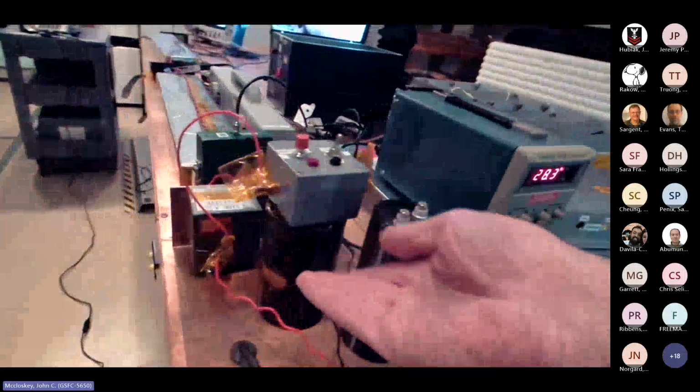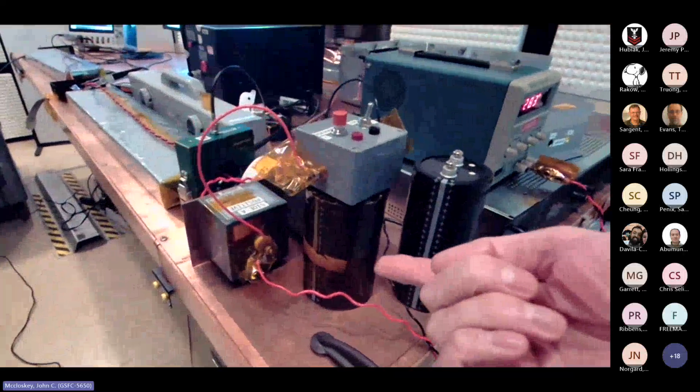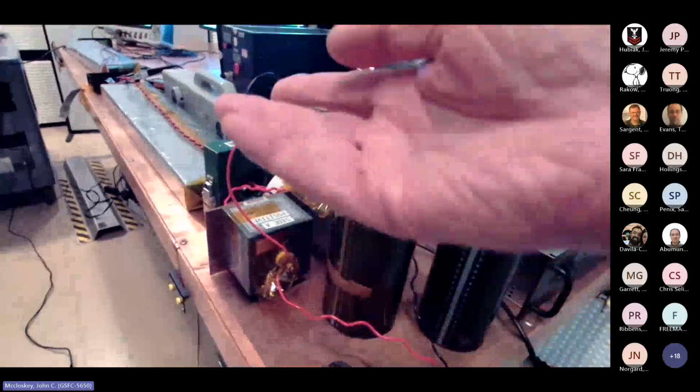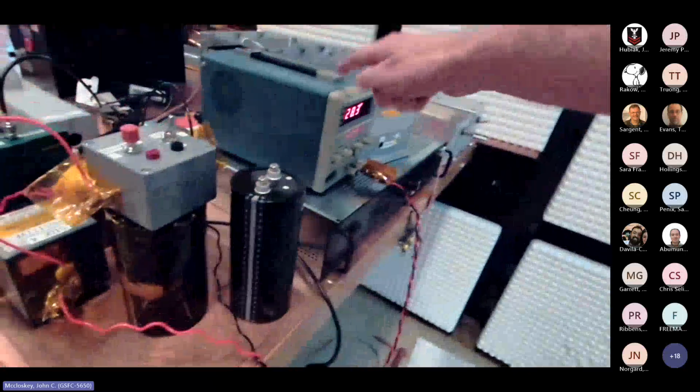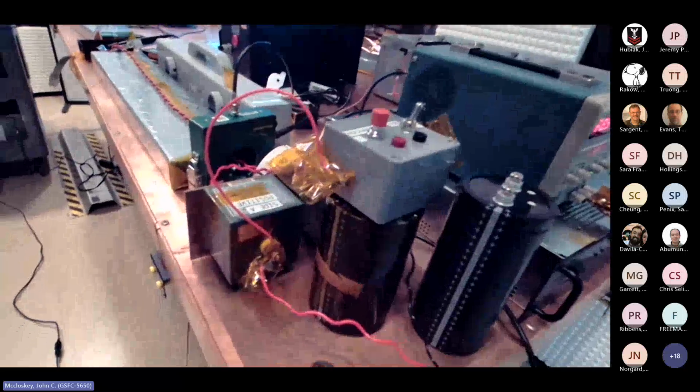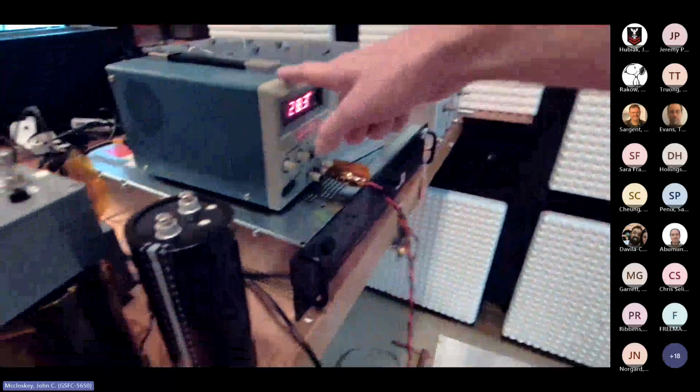It's essentially the same as putting decoupling capacitors next to your ICs on a PC board, so that the high frequency currents are drawn from these capacitors and not from the supply. So the source impedance that your EUT sees is this, not this.